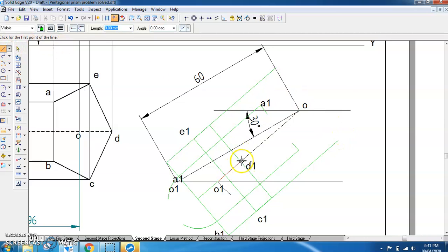Similarly from D1 you can get 45.96, enter, and you can have the line parallel to this O1. Like this O1, it is on the same line. Or else you can have 90 degrees to this. Here again the constraint command will be there; a different constraint it will take at one point. Like this. Now you have got all the points here, just connect them.